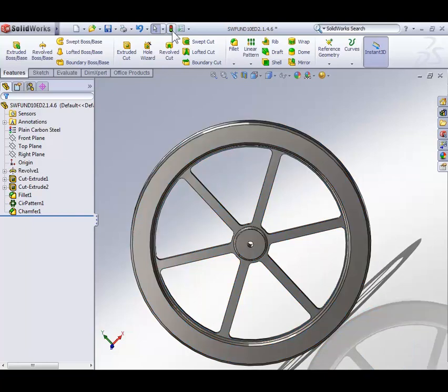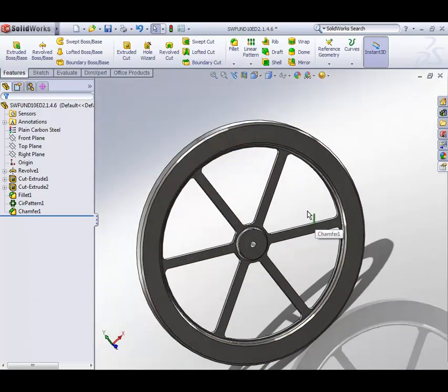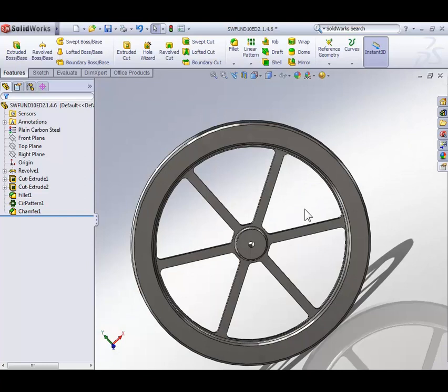When you do, there are a few things that I want you to notice. First, the whole flywheel grew to the new size. Also, the inside bore grew with the outside diameter. And that's because when the part was modeled, we captured our design intent. So, as we change the model, it maintains our design parameters. And this is what we refer to as parametric modeling.